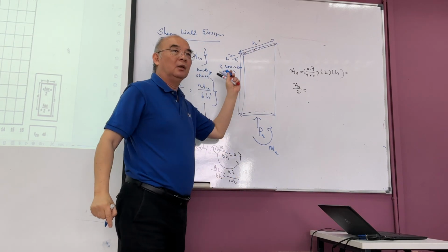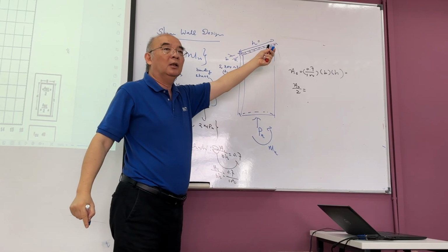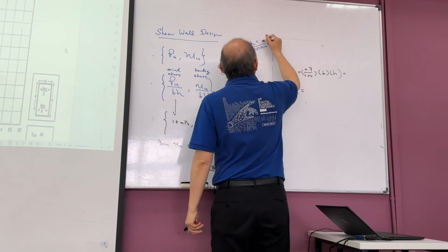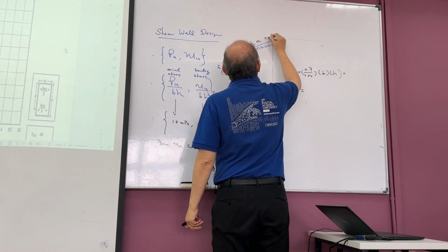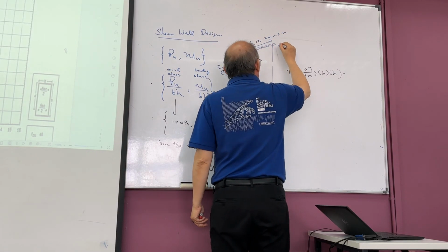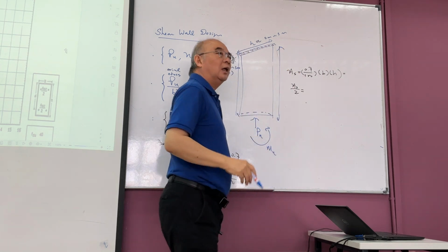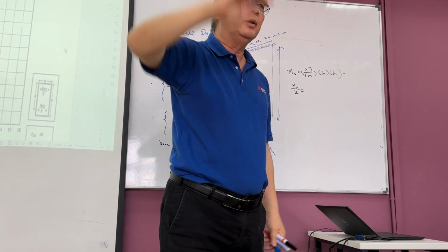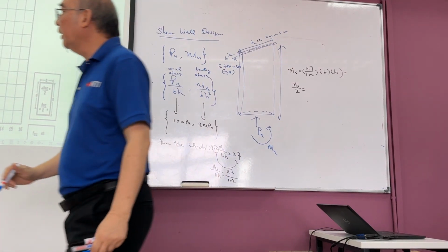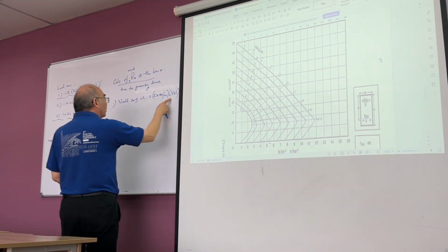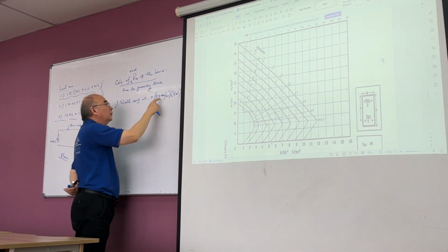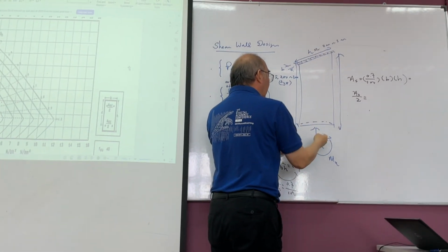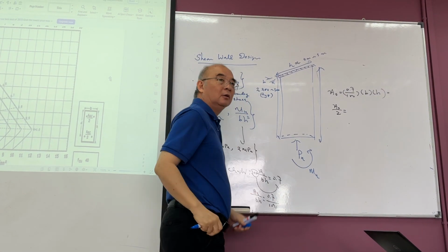This length here could be 2 meter, 3 meter. So typically it is 2 meter to 3 meter. The height will be in the tens, 20, 30, 40, because it depends on how big this will be. Understand? So based on the 24 kilonewtons per meter cube, and the volume, you get the entire self-weight of the wall, right? Of the wall.